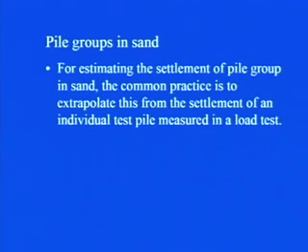You have already seen how this load test is performed in the field on a single pile. So you know how you can get the load settlement curve in case of a single pile. When you find out the settlement of the pile group, you can extrapolate the result of that individual pile in case of sand.